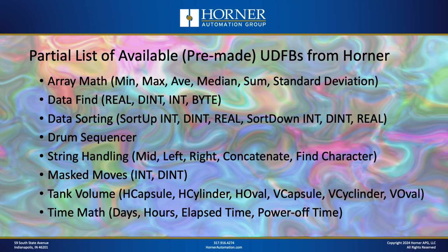Here's a summary page that tells you in one location all the different categories of UDFBs we've done here on this channel, as well as what some of the individual functions are within that category. So you can see we've got quite a list here. Now, the first several operate on arrays. Okay, so array type variables, and of course array type variables are only available with variable-based advanced ladder and IEC. They're not available in register-based languages.